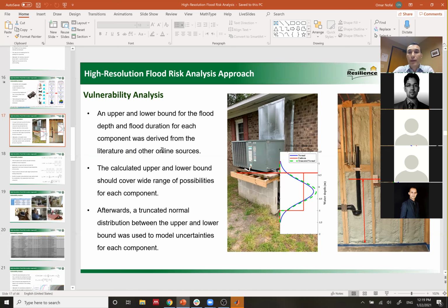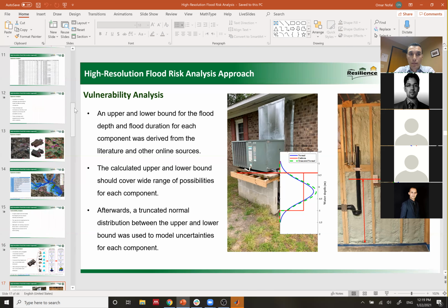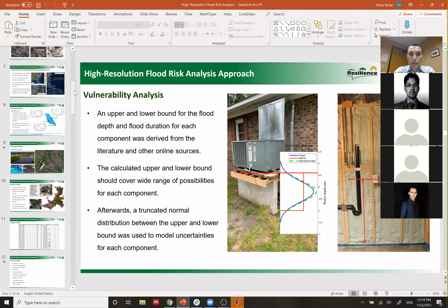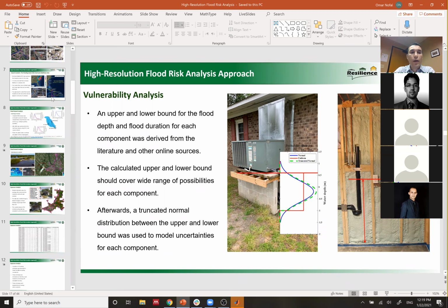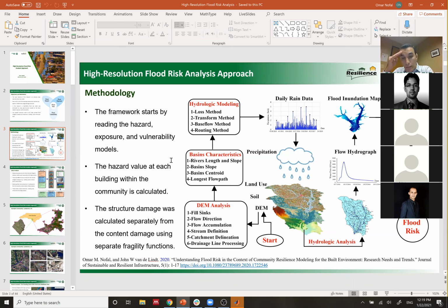All right. Just one more question, and I'll conclude. Go ahead. You said in the beginning that you had considered three maps: one is the elevation, the other shows the occupancy, and you also used a soil map, right? What we have observed in the last few floods here is that in some buildings there is a lot of scour at the foundation level, due to which the building gets damaged. So, have you considered soil for any other reason in the current research?